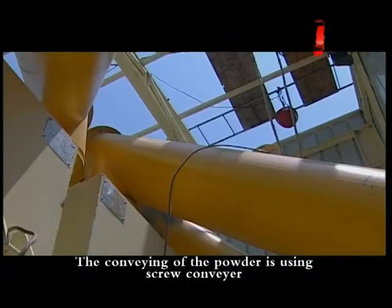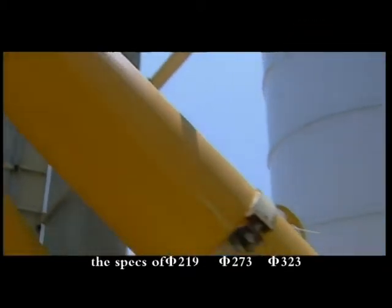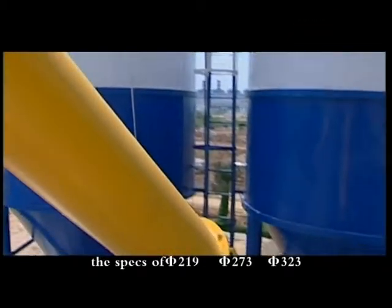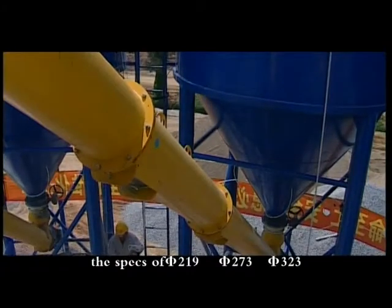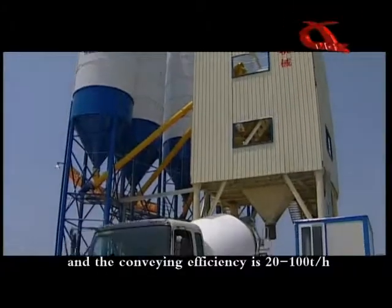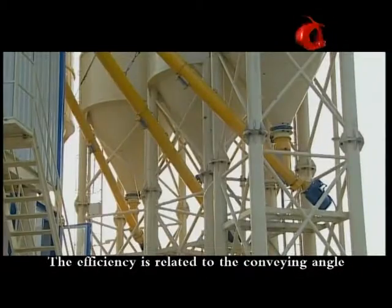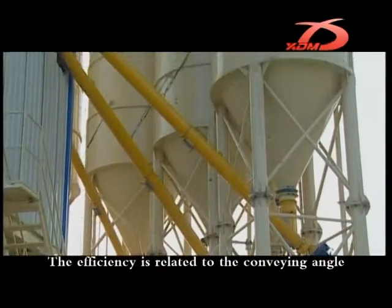The conveying of the powder is using a screw conveyor, with specs of 219, 273, 323 diameter, and the conveying efficiency is 20 to 100 tons per hour. The efficiency is related to the conveying angle.